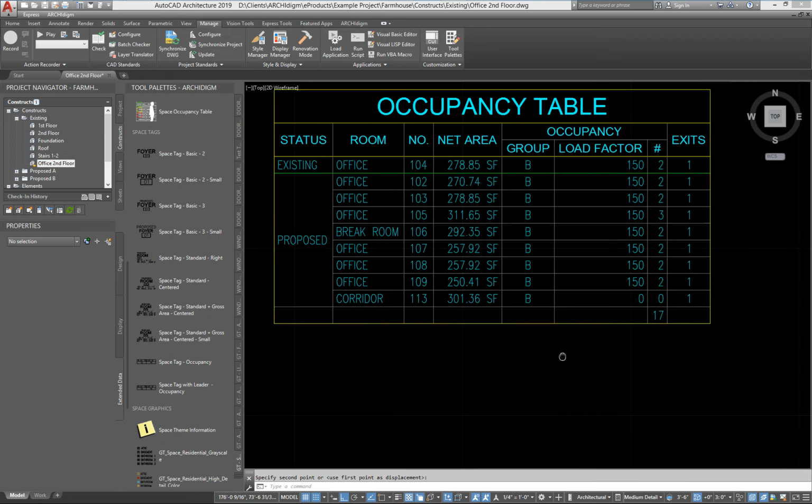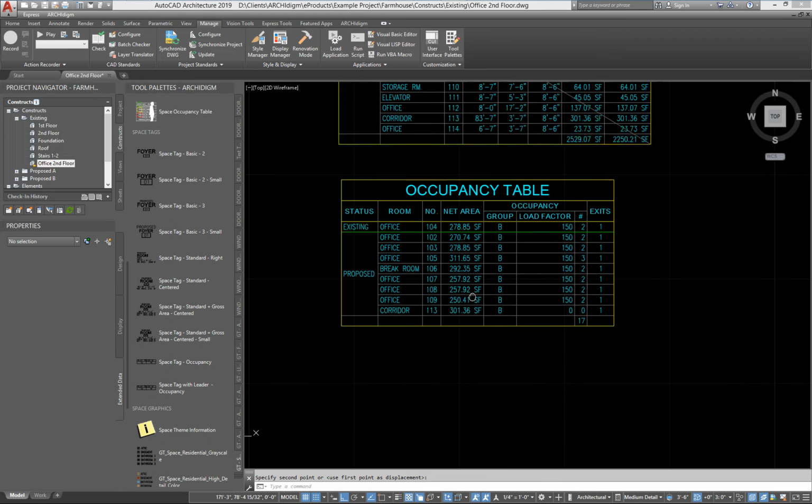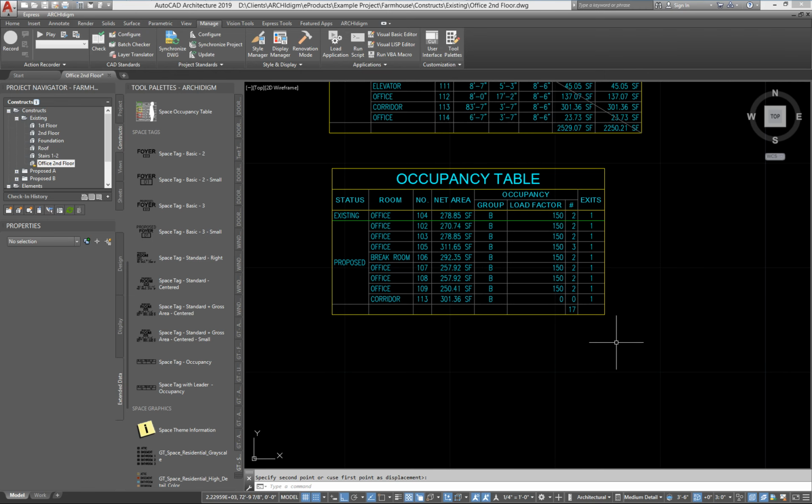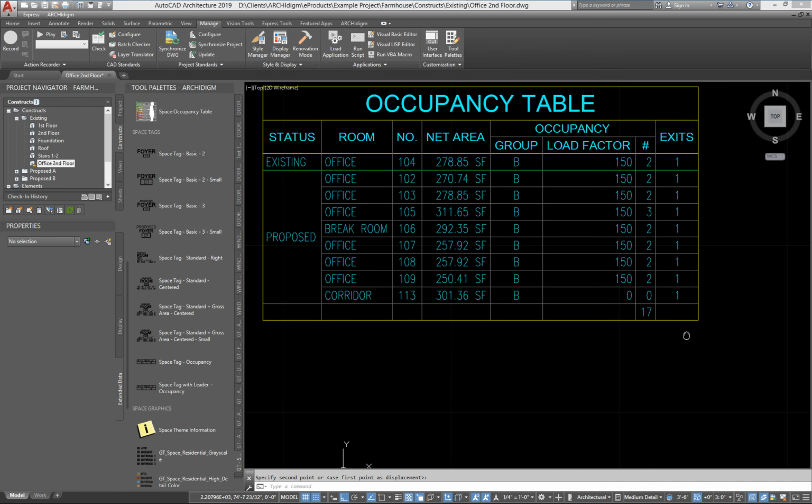See, I don't do my tables with places that have no occupancy. If there are no occupants, I'm not scheduling it. But at least you could see how you can go in there and make a modification. And what would you need exits to become? It still needs exits.